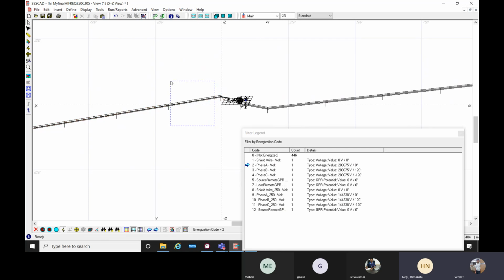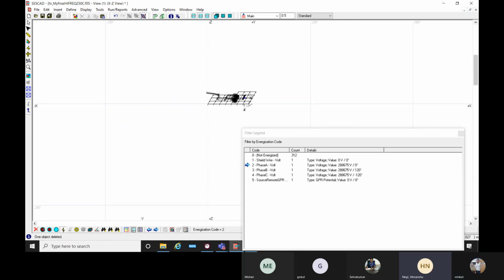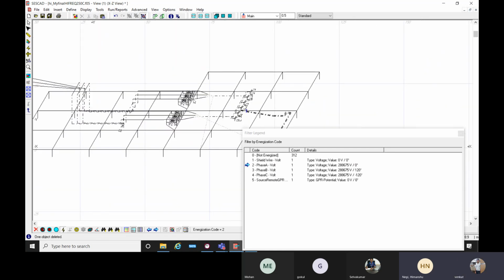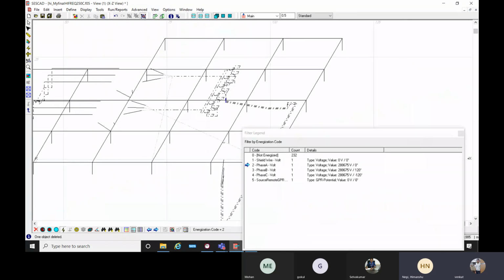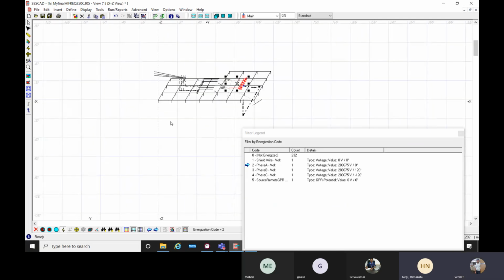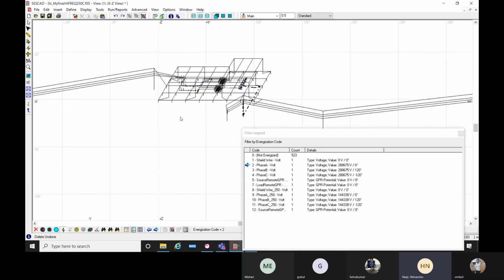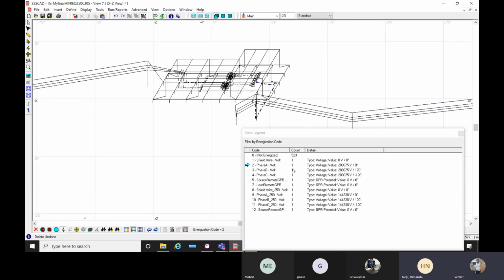Only they do it. Other people will just create something like this, right? No transformer, nothing like this, just a mat and this GIS, for example. So in this case, if I model this or if I don't model this, it makes no sense. This will only work if I create a voltage source like I did before. Then my source is there and I can create any fault in the substation and I can generate the same phase to earth fault level like the utility gave me.